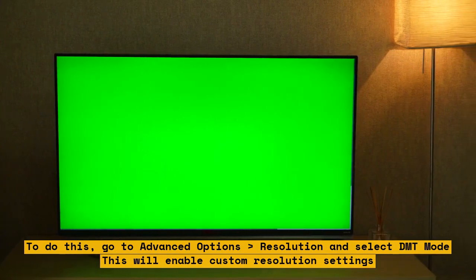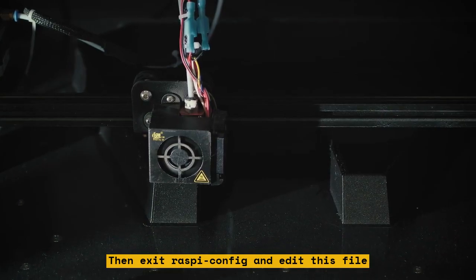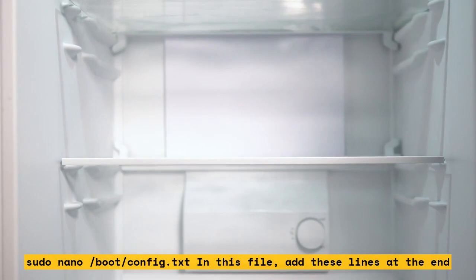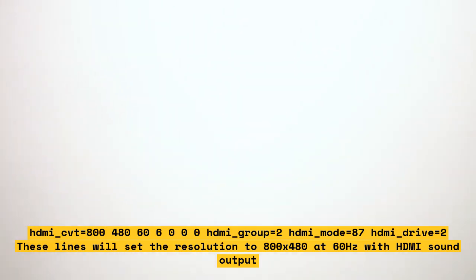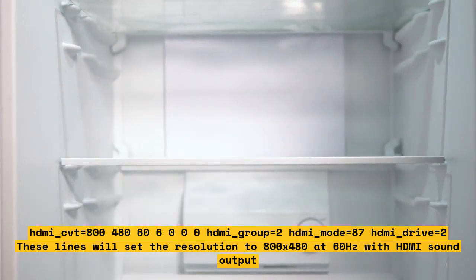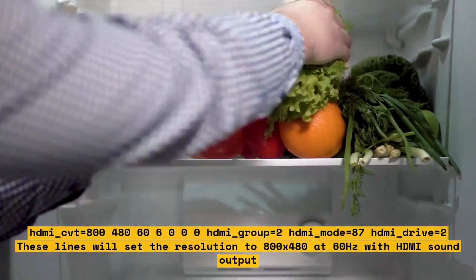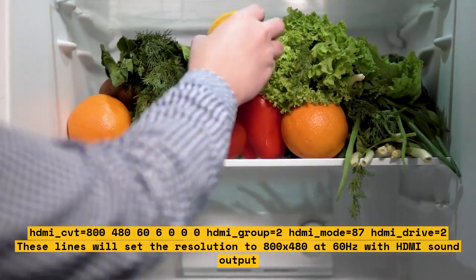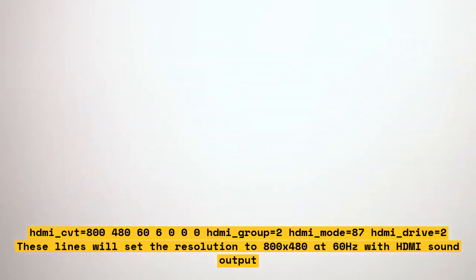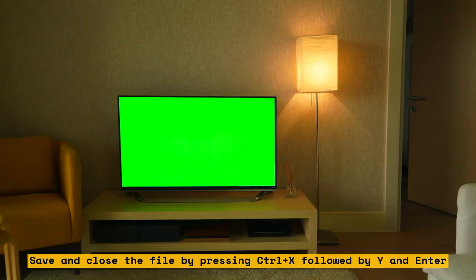Then exit raspi-config and edit this file: sudo nano /boot/config.txt. In this file, add these lines at the end: hdmi_cvt=800 480 60, hdmi_group=2, hdmi_mode=87, hdmi_drive=2. These lines will set the resolution to 800 by 480 at 60 Hz with HDMI sound output. Save and close the file by pressing Ctrl+X followed by Y and Enter.